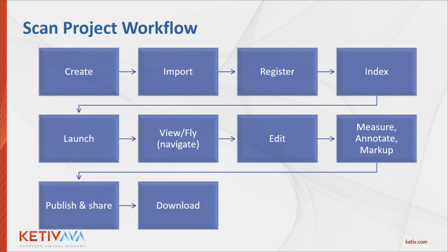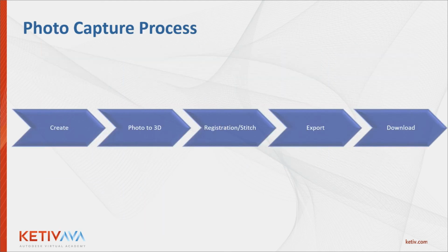So there's a few more steps when you're looking at laser scanning and doing maybe drones, depending on exactly what devices you're using. If you're looking at doing photos, then it's somewhat similar, but a little simpler at the same time: you create your project, you bring in the photos, and I'm going to show you some examples I did from my own iPhone. Again, you do have to upload it and have it stitched together and registered, if that's what they call it. And then you can finally export or download it as well, so you can reuse it. So those are the processes that you would have to use for this.